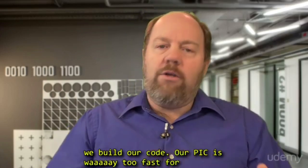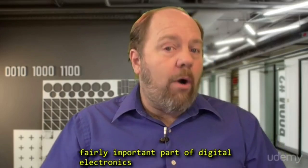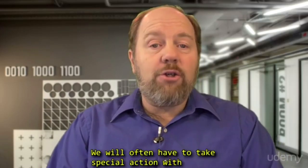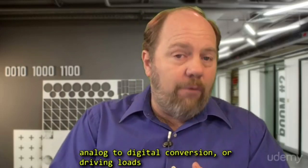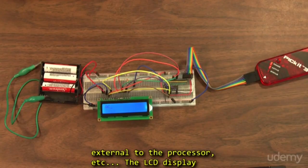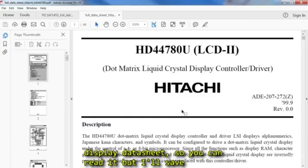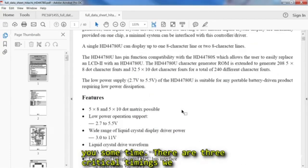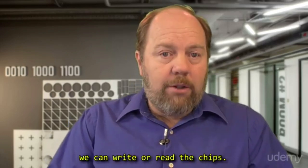There's some things we need to account for before we build our code. Our PIC is way too fast for the LCD display. We now need to take into account a fairly important part of digital electronics called timing. We will often have to take special action with digital electronics, especially for things like analog to digital conversion or driving loads external to the processor, etc. The LCD display is no different. Now, this is all buried in your LCD display datasheet, so you can read it, but I'll save you some time. There are 3 critical timings we have to watch out for. The first one is the fastest we can write or read to the chips.